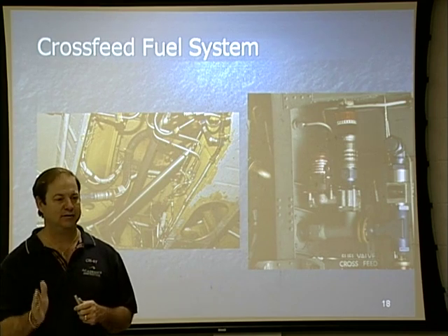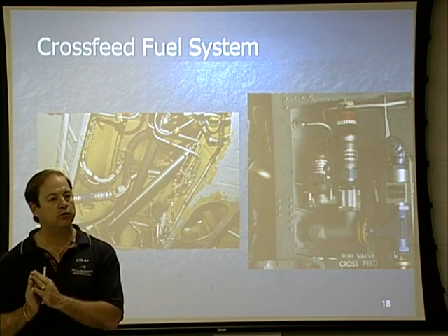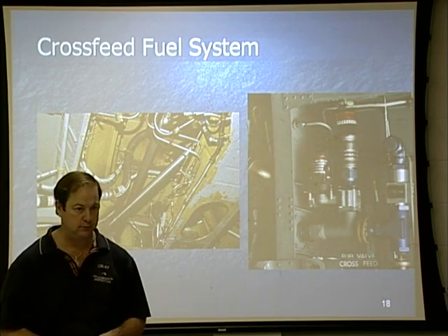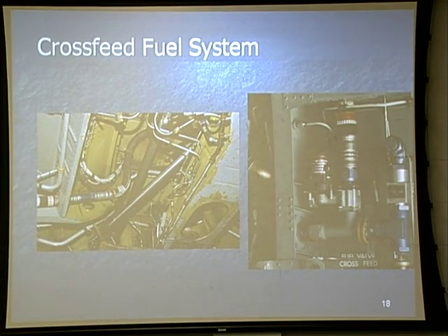But we are not transferring fuel from one side of the aircraft to the other side, and we are not transferring pressure from one side to the other side. In actuality, you're going to find out we don't even pressurize our tanks. All we're doing is sucking that fuel out, and we're pressurizing it in the line up to the engine. That's what's happening at the pumps, contrary to popular belief. People are under the impression that we are pressurizing the tanks. We are not pressurizing the tanks. We are pressurizing the fuel in the lines up to the engines. Any questions about that?